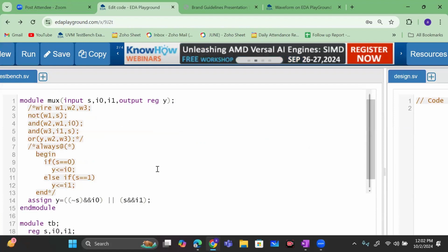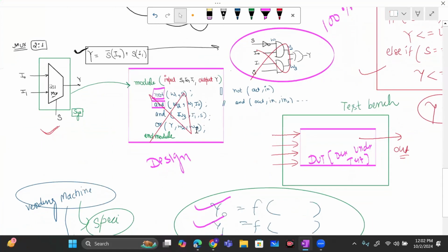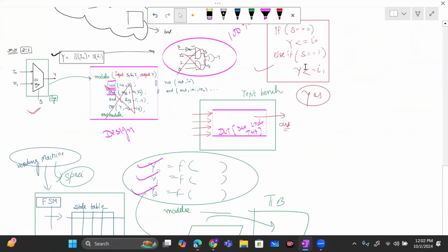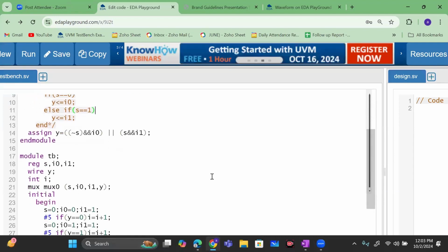What we saw was the actual process and the actual steps of how we cover a circuit, from specification to the entire front end: the behavioral, the data flow, the gate level, the test bench, the self-checking test bench. We have many things. We have task-based test bench, and we have methodology as well.